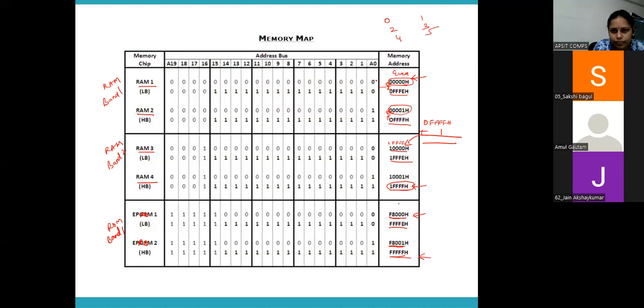So you can see here, this is 00000H. This is 00FFEH. So you can see here, this is 0FFFE, right? This is 00001. This is 4 Fs. So you can see this is 0FFFF. So what you have written here is nothing but the expansion of this memory address. This is 10000, 1 followed by 4 zeros, right?